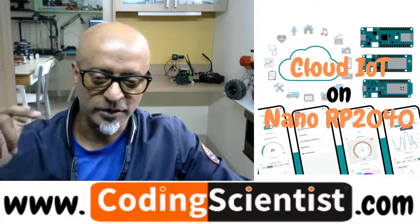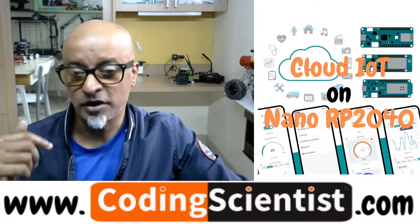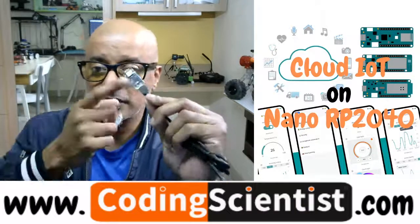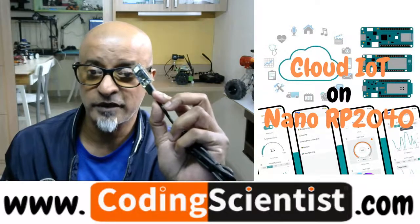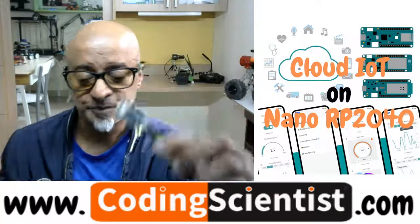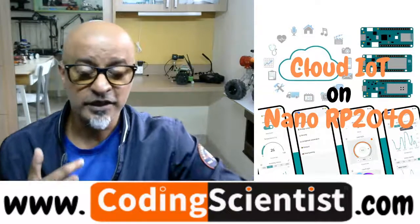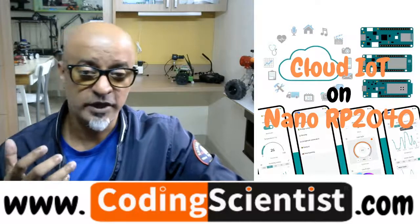Either it should be CircuitPython or it should be your Nano RP2040 chip. But according to me, it should actually select this board. We have written the CircuitPython firmware into this in the previous lesson, right? We did download the firmware and put it into this. That was successful, that's pretty much working. But this IDE should actually detect it. Anyways, it is detecting CircuitPython at the bottom, but it's not showing RP2040 Connect and so on.